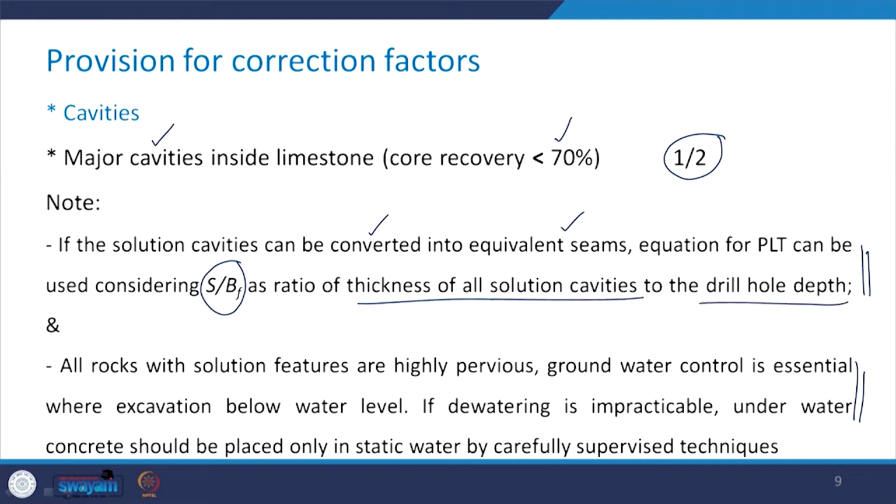In case all the rocks with solution features are highly pervious, groundwater control is essential where the excavation below the water table is there. Now if dewatering is impracticable, then underwater concrete should be placed only in the static water by carefully supervised techniques.